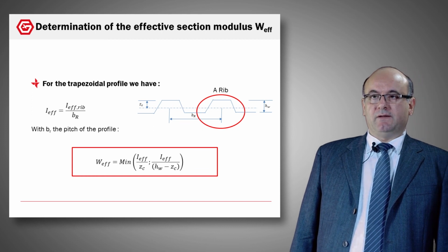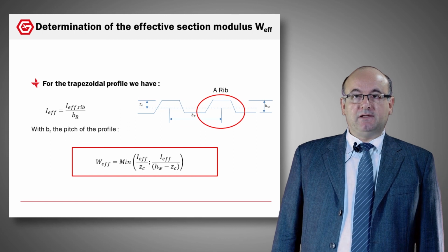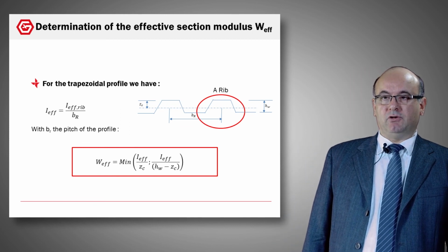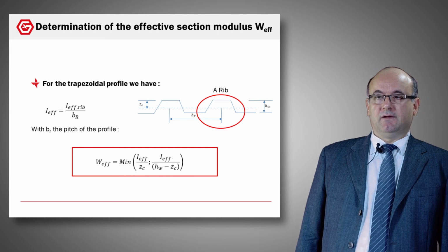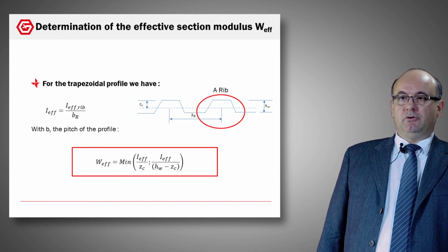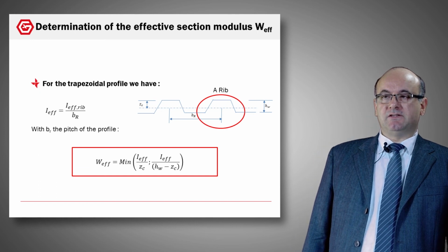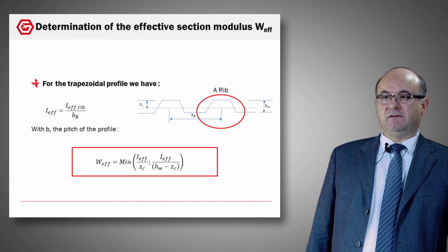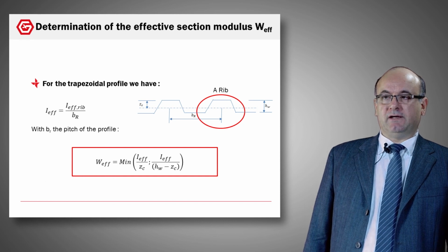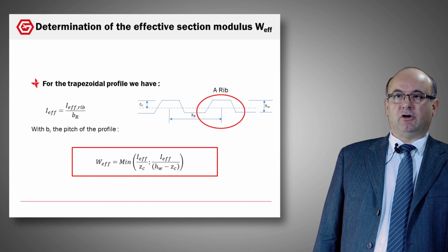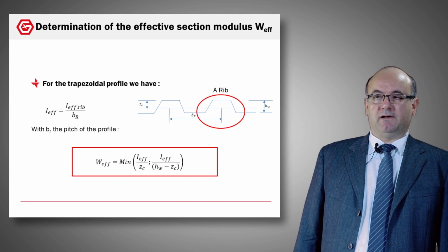So we correct the table, and after we now have the possibility to calculate the effective inertia of the profile by using the Huygens formula that is given on the bottom. I remind you that we study a half of a rib. That is why, to cover a global rib, it is necessary to multiply the result of the effective inertia by 2. And don't forget to multiply by t if we make the calculation of the length only and not on the area of each part of the profile.